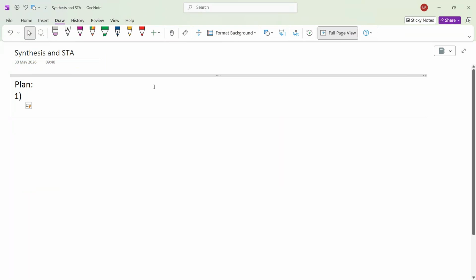We will be starting with synthesis flow and run the synthesis. In that, there are different optimization techniques that the tool is doing. What all optimization techniques the tool is doing from inside, because some of the optimization techniques we can activate, and we can also tell the tool not to do certain things.